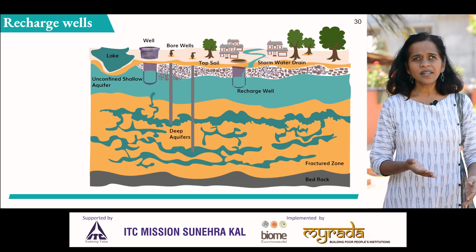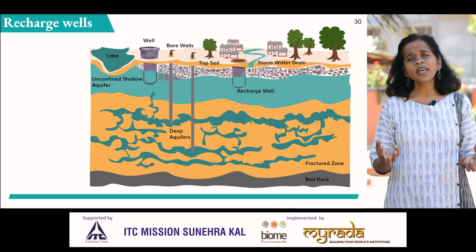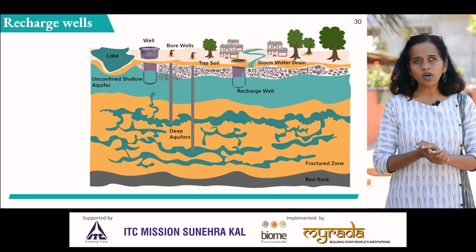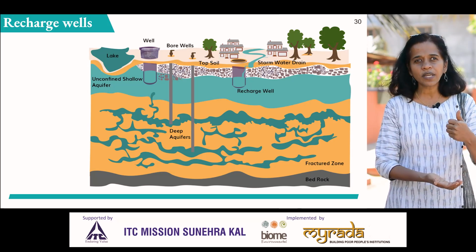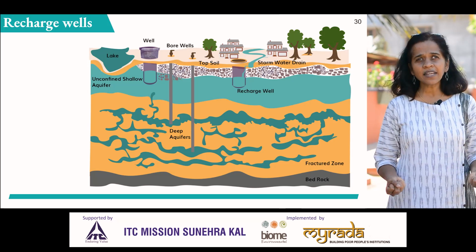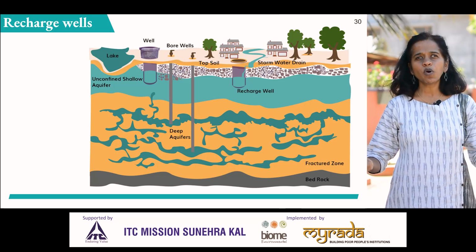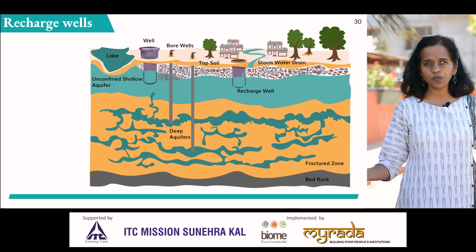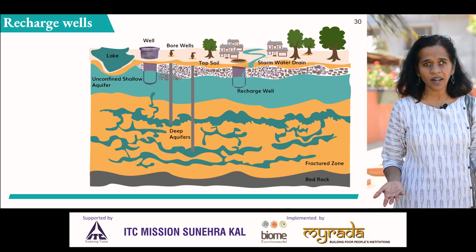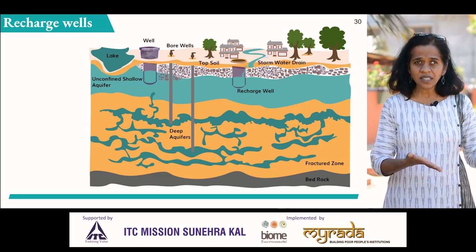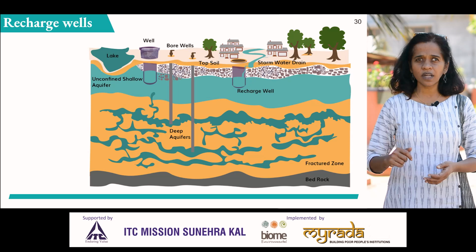When we go below that, that's where we hit what is the weathered zone in Bangalore. The weathered zone, think of it as rocks that have eroded, weathered over a period of time and have attained a kind of sandy structure. This is soil that you're able to break through very easily, which is really like a sponge. So when we put water into this layer, the soil is able to absorb the water, hold it as well as allow for it to flow. Very simply, we can imagine that this is where our shallow aquifers are. Earlier, when people dug open wells, this is where they got their water from. And this hence is a good zone to put water into the ground as well.